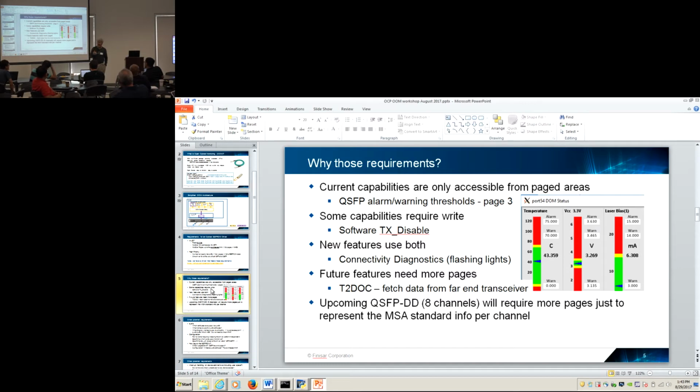Okay, so for the folks online, Steve asks, how many people think we do need a new driver? In particular, QSFP-DD is probably going to be available within a year. Plus these other things, do we need a new driver? Hands up. I might add that there's another competing mechanical interface called OSFP for octal SFP. And we don't know which one's going to become popular between QSFP-DD or OSFP. So some people in the room may be going towards OSFP, but we're not trying to exclude. But either one will be basically I2C, paged, and has exactly this set of questions and issues.